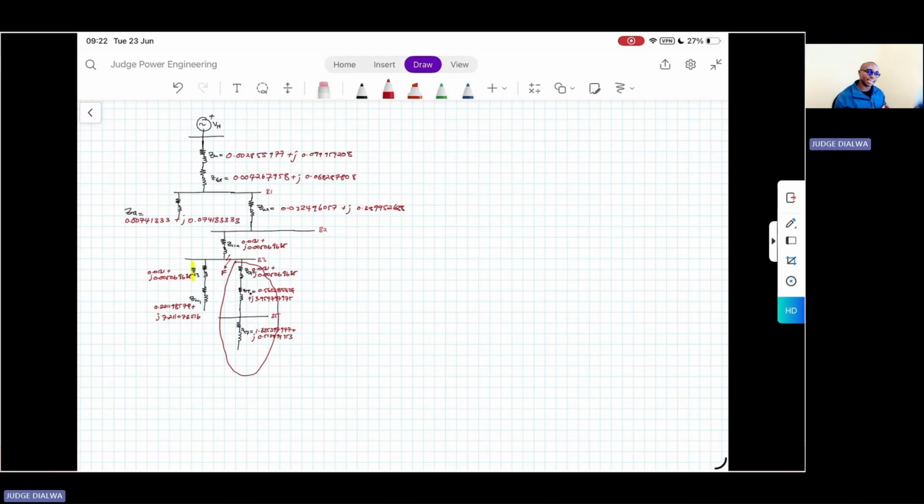However, if it had an induction motor or a generator, even if they were running unloaded, we would still include those in our analysis because that would be a voltage source behind an impedance. That's why I said it's important that we understand the statement of what impedance to consider: the impedance between the voltage source and the faulted point in our network. So in our analysis, we will not include the branch that I just circled in red.